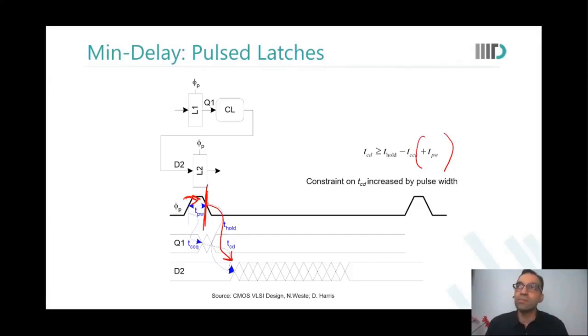See, in a typical system, when you have to design an ARM core or anything, you cannot really have such short pulses. However, if you're designing a very specific system where you're using only latches all over the place, and pulse latches are that, then you may say that, okay, instead of having a pulse generator in every latch, I would rather use a pulsed clock. That is what we're talking about over here.